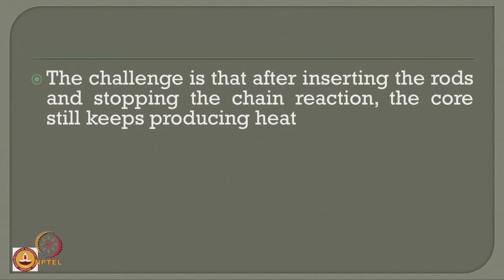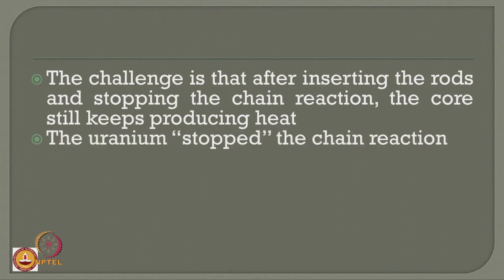Now, the challenge is that after inserting the rods and stopping the chain reaction, the core will still keep on producing heat, because you cannot stop that heat production from the core. Okay, the moderator rods have disconnected the chain reaction, but the core still keeps on producing heat. Actually there is no reaction happening, but heat is there. This heat has got to be removed.